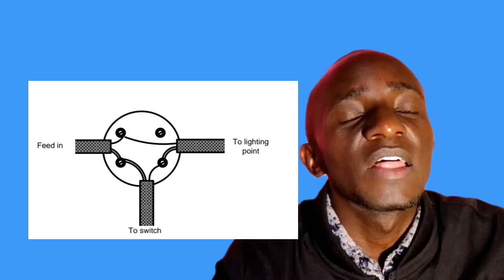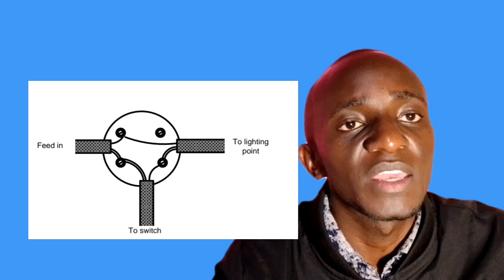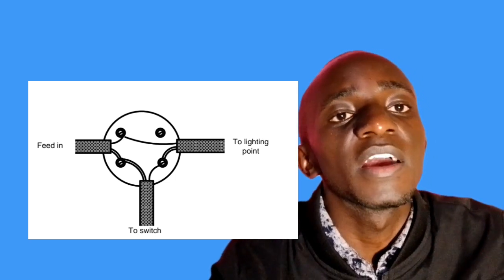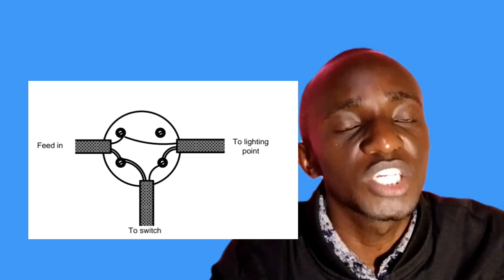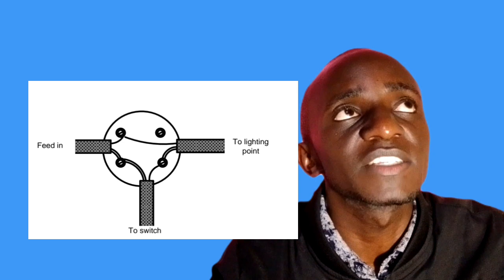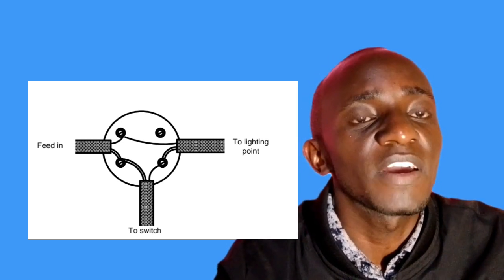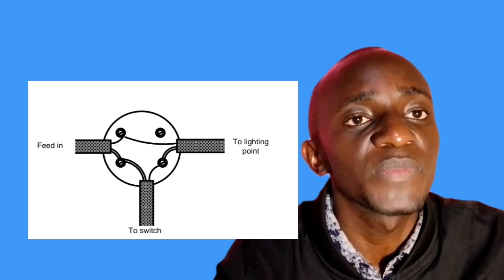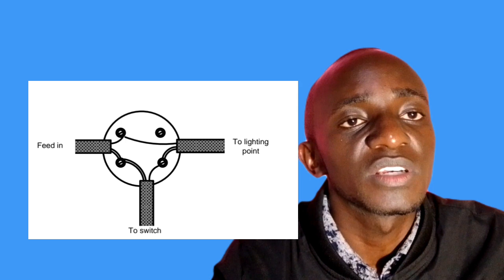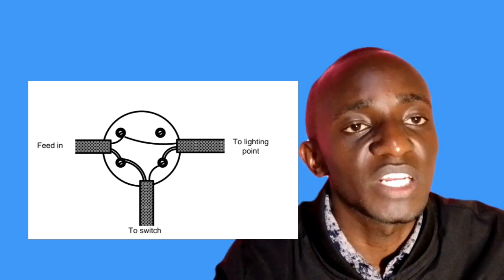Then the live terminal from the supply is joined with the live terminal to the common part of the switch, and also joined to the terminal that is going to supply the next lamp. So we have those three cables joined together and maybe terminated in one of the blocks if the joint box has a block, all insulated.